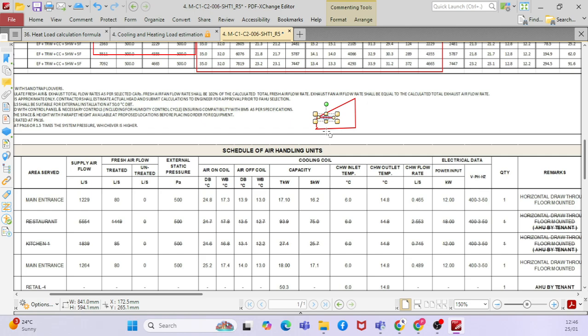Clear? Yes, sir. So when you try to cool the air, it will go and meet the saturated condition. It will not go exactly the same. It may go a little bit inclined, because you have both a sensible load and a latent load, right?